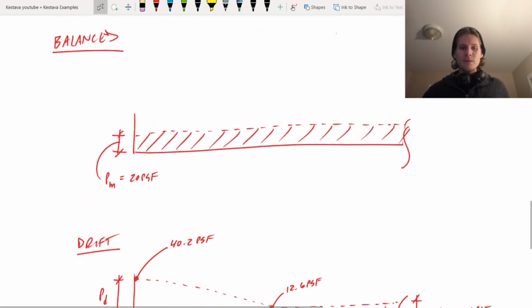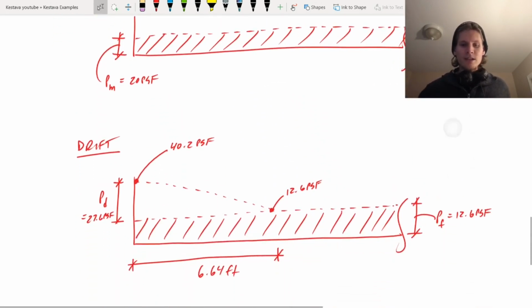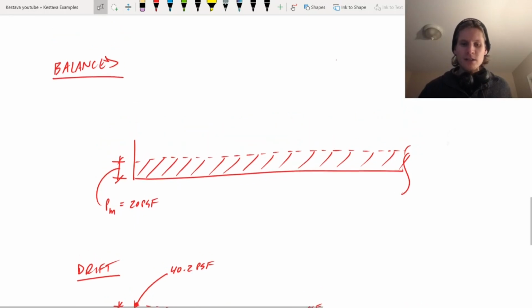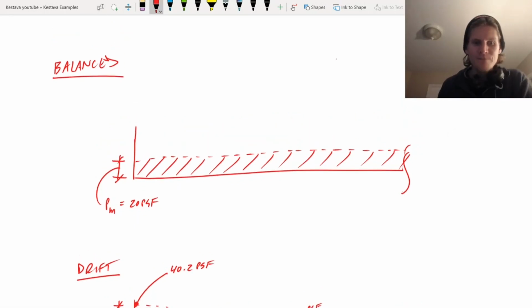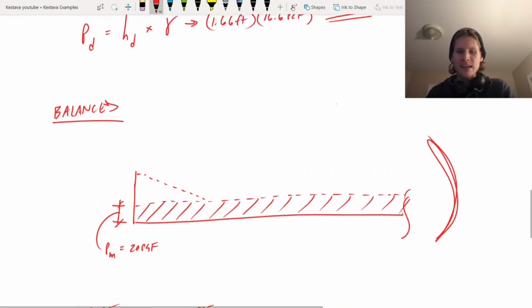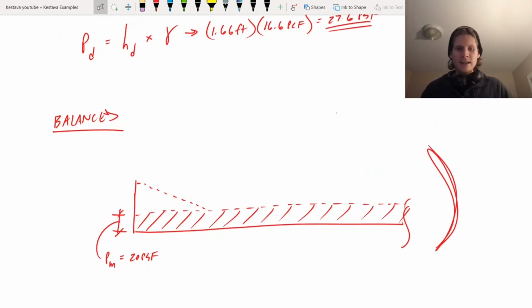And right above was our balanced snow loads. Now you don't need to combine them, which is why we held on to balanced P min and flat roof P sub F for so long. You don't need to double dip here and be overly conservative and say, well, P min was easy to find, so it's 20 PSF, and then for that same condition also stack on the roof snow drift criteria. You don't combine them for the same design. They are separate from one another because that would just be overly conservative.